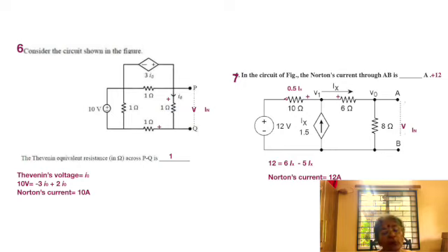Now we can balance the voltages. We can say that 10 volt is equal to, let's take the outer circuit, the 3I0 voltage, which is oppositely directed, so it's minus 3I0 as far as voltage balance is concerned, and then we also have I0. Please recall the earlier directions that I gave you, wherein any resistance in parallel with the voltage source is irrelevant.